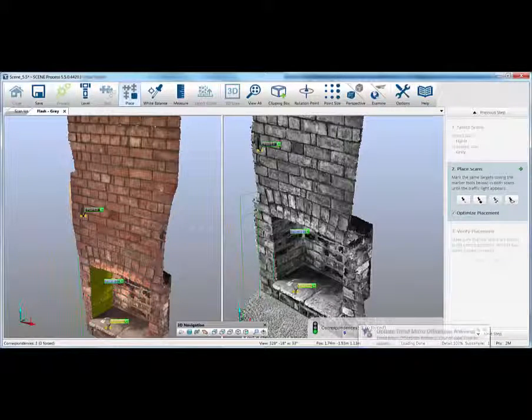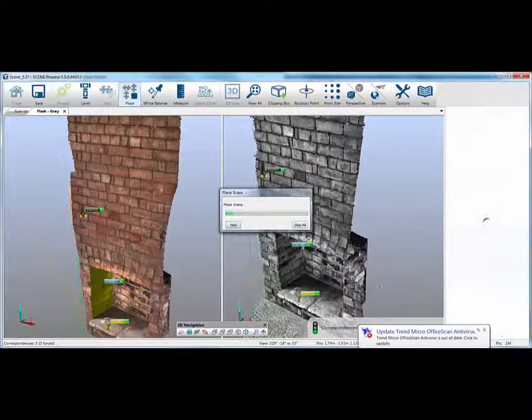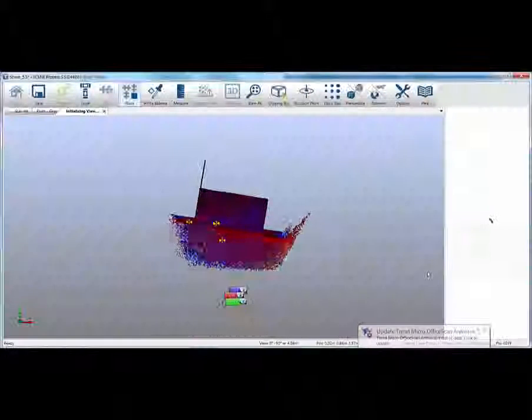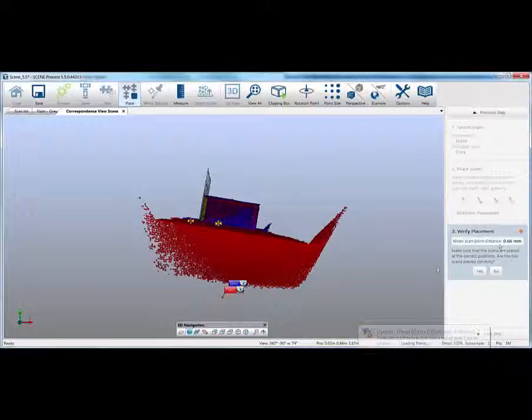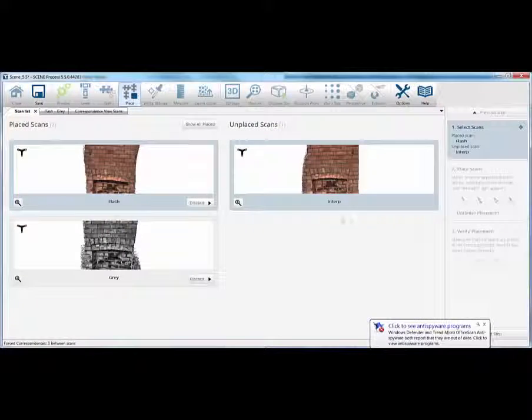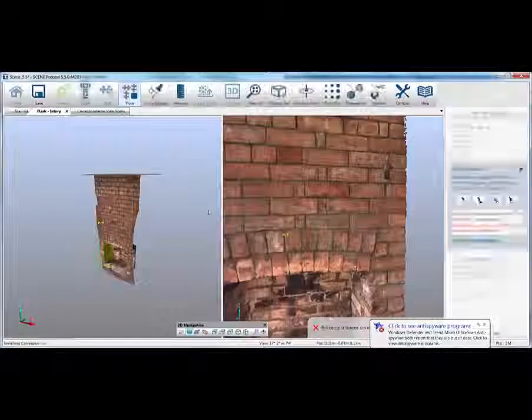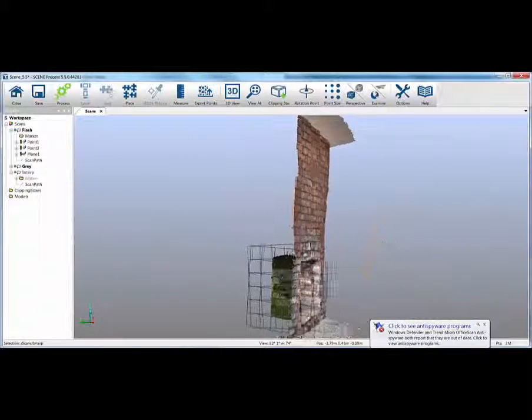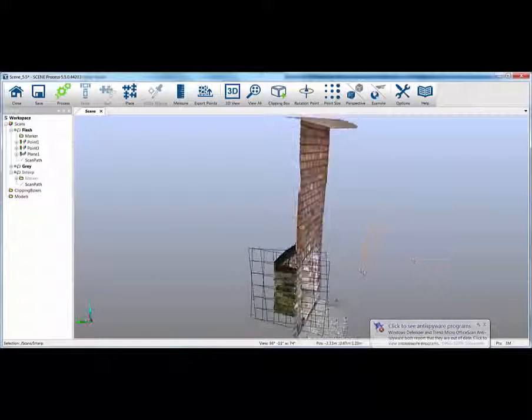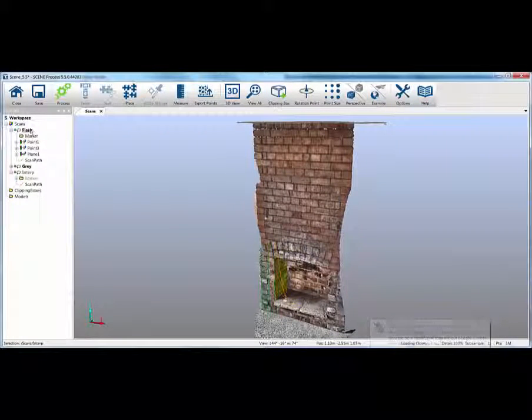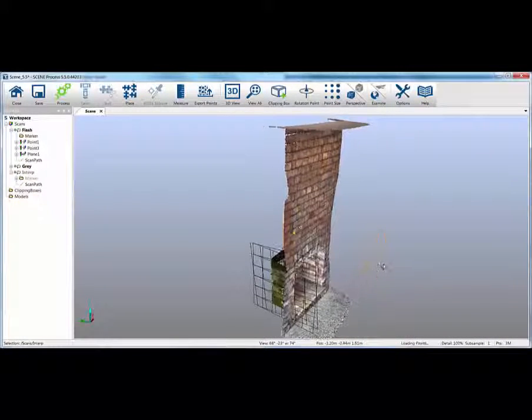Now that also applies to full scene 5.5 as well. Again, the features between the two systems are identical, so you're getting the same level of features. I'm just going to click next steps on here. It will go through, it will do its rough registration, then it will do its cloud to cloud. So click OK, and I'm just going to close that down, and here you can see we've got the overlap between the colour in flash form and the grayscale over the top of one another.